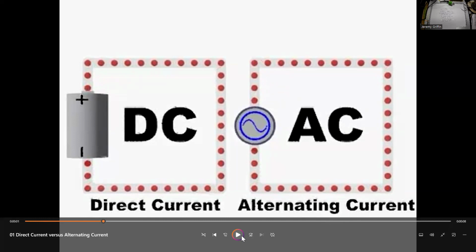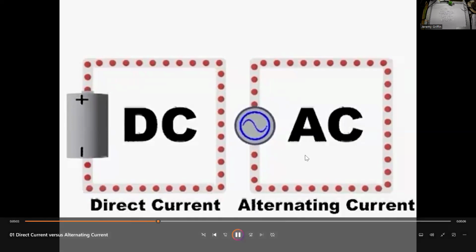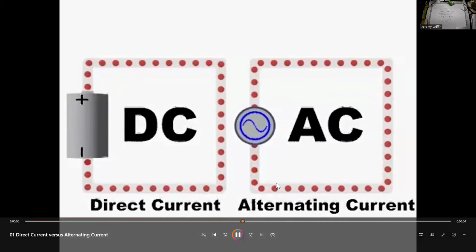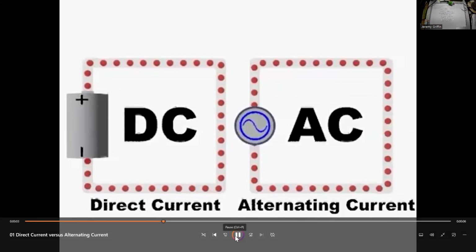Okay, so great. A power plant has to submit probably some number of megawatts to an entire community, right? So a lot of watts are going out, but that I is ideally small, right? You don't have a lot of current flowing. But the only way to do that is to pump up that V, that voltage, to like thousands of volts. And then you can use what's called a transformer, we'll talk about in a couple of weeks, to step, in this case, step down the voltage from like thousands of volts down to, do you guys remember yesterday what I said, what was the alternating current voltage standard in the States?